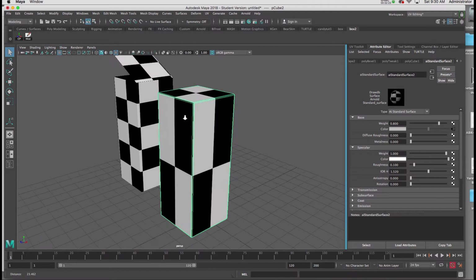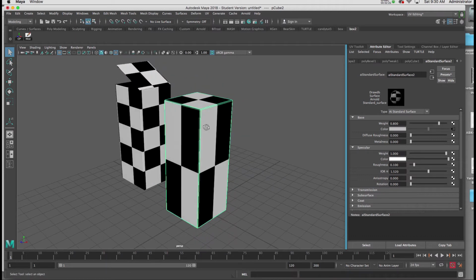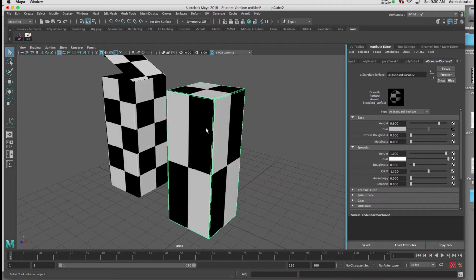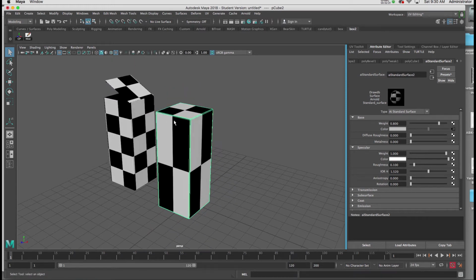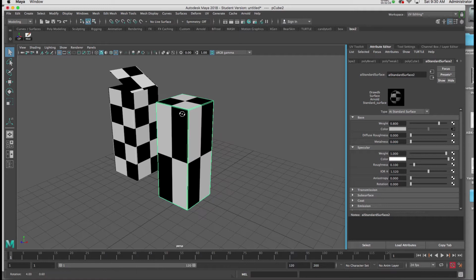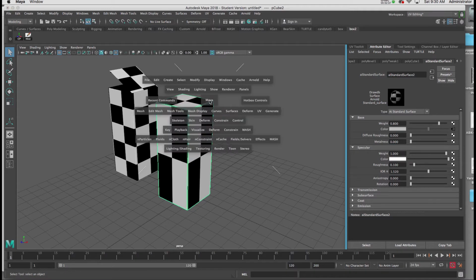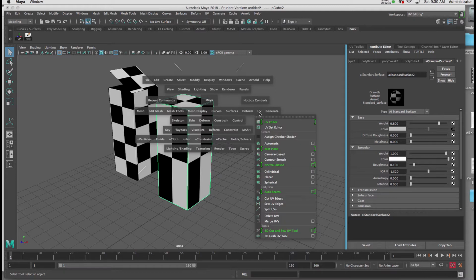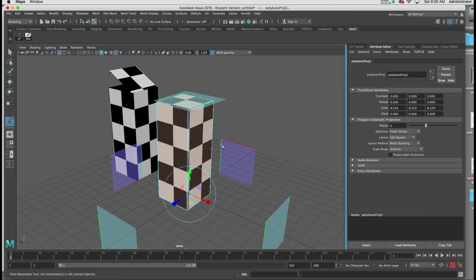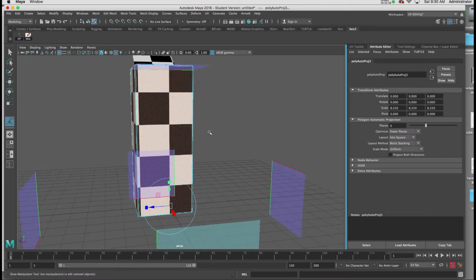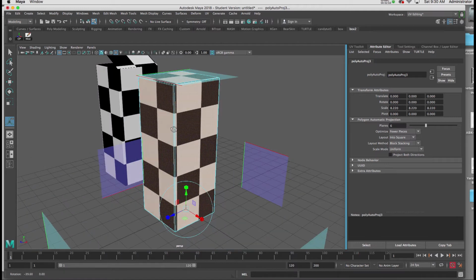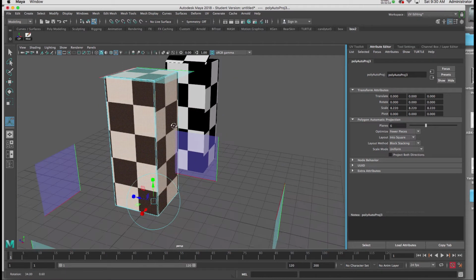And that will assure me that the shape of my faces will be accurate inside the UV texture editor once I've used automatic mapping. So with my geometry selected in the object mode, I'm going to hold down the space bar, I'll go to UVs, and I'll choose automatic. And you'll see the checkerboard pattern appears on your geometry with the boxes all pretty much evenly distributed and